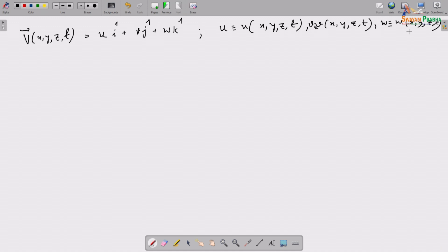Okay. Now this is a typical velocity profile that we know, and we can plot and we can do things. And just now I said that terms like del u del y, and del u del z, are going to cause turning of a fluid element, whereas del u del x or del v del y is going to stretch the fluid element. So that's what we just said.